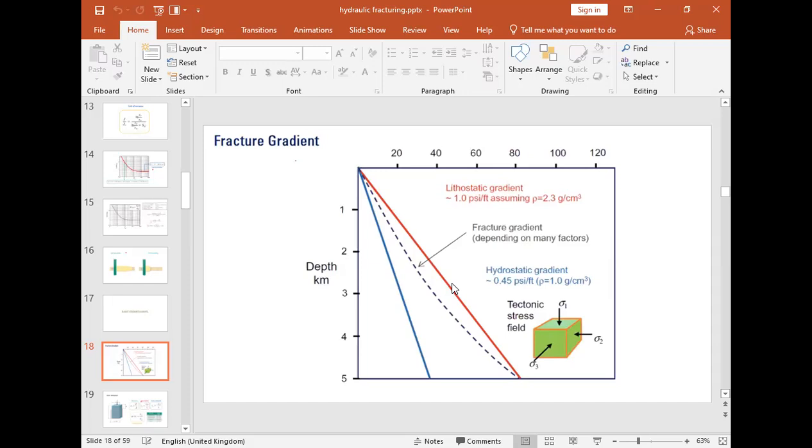It's not just any company that can carry out such drilling, because there is a narrow window between our pore pressure and our fracture pressure. You have to manage the pressure within each zone so that at the same time it is higher than the pore pressure and lower than the fracture pressure. That is outside what we are discussing at the moment, because we are talking about hydraulic fracturing.